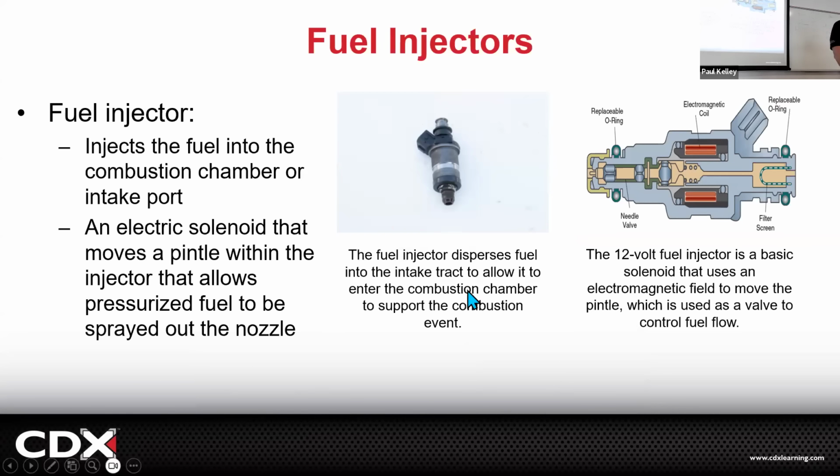All right, and then injectors, I think we could go wild into all the details, but I think you'll get the important points. The injector's job, it gets fuel pressure into the top. That's where it gets its fuel. In the top, typically there's a little screen. Why do you think there's a fine screen right there? Exactly, and it does sometimes catch stuff.